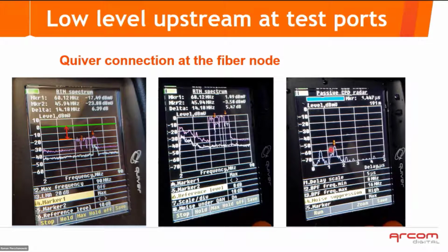Take a look. This one is minus 55. If it was 20 dB down, it was minus 75. It was like one of these blips here. And this one was not visible at all. Here we revealed them and we traced the CPD source and fixed the problem. And it was not back.